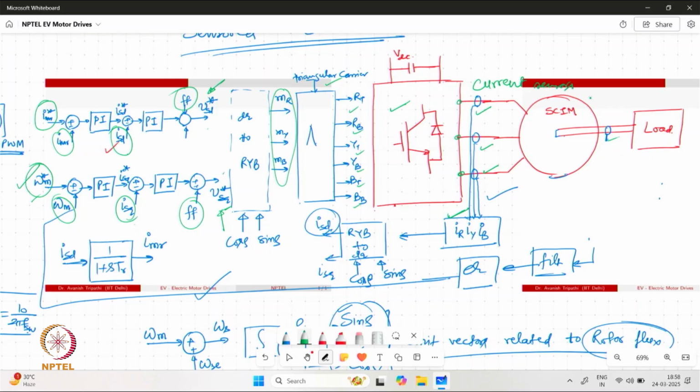current sensors. Typically we have Hall effect current sensors used for this purpose. We may measure either 2 or 3 or all 3 currents based on what type of system we are dealing with, and then eventually converting that three-phase current to DQ, ISD, ISQ. Now, once we have ISD current available with us, we can use the rotor flux model and we can get the IMR value. Now, once this value is achieved, the flux control loop can run sufficiently.